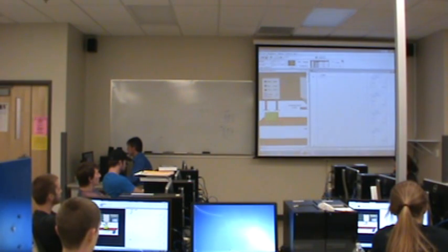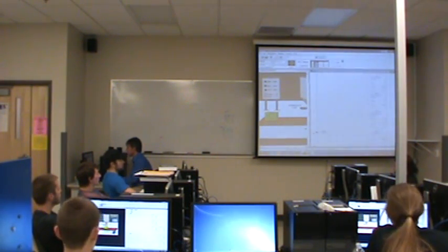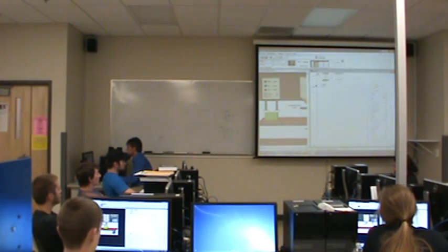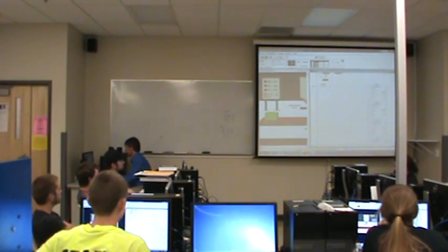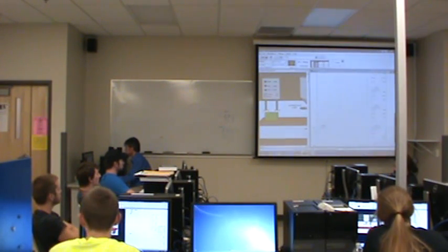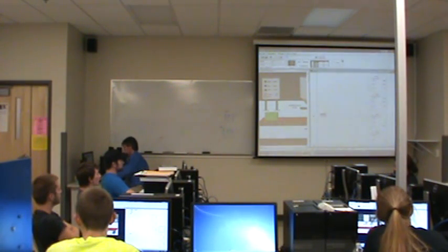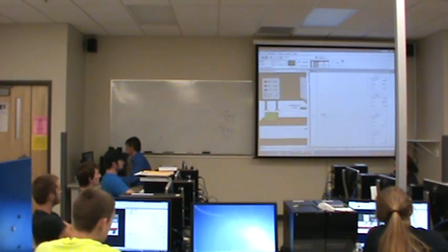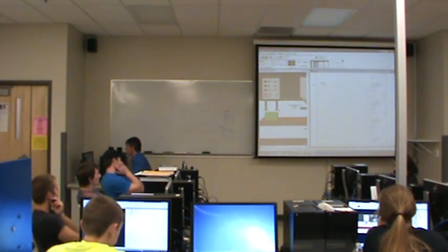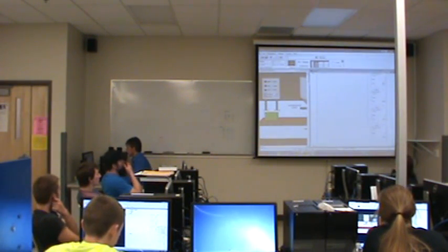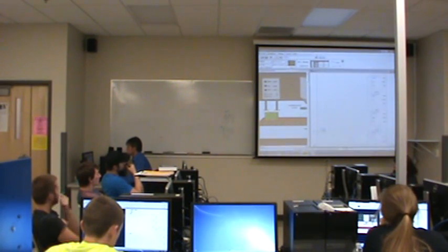Now let me rearrange these because I would rather have the inputs list first and the outputs last. That will make more sense to you. And to keep it really clean, I'm going to change the bit numbers. Switch those around as well. Just changing some references. So here's the outputs list. It references address 11, 12, 13, 14. The input list is still too long.